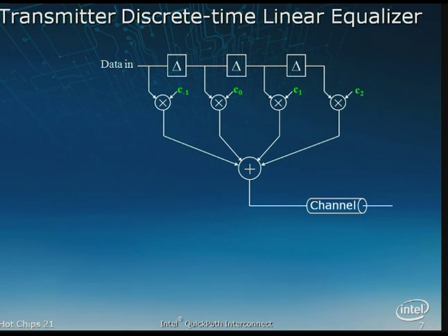Transmitter equalization. For some of you computer architects out there like me, I thought this was a very enlightening area. This is not my area of expertise. That's my next disclaimer. What is equalization and why do we need it? Ultimately, all lanes, our channels, are slightly different. And all this equalization thing is, from an architectural standpoint, is multiple taps via some delay lines, or delays, I should say.